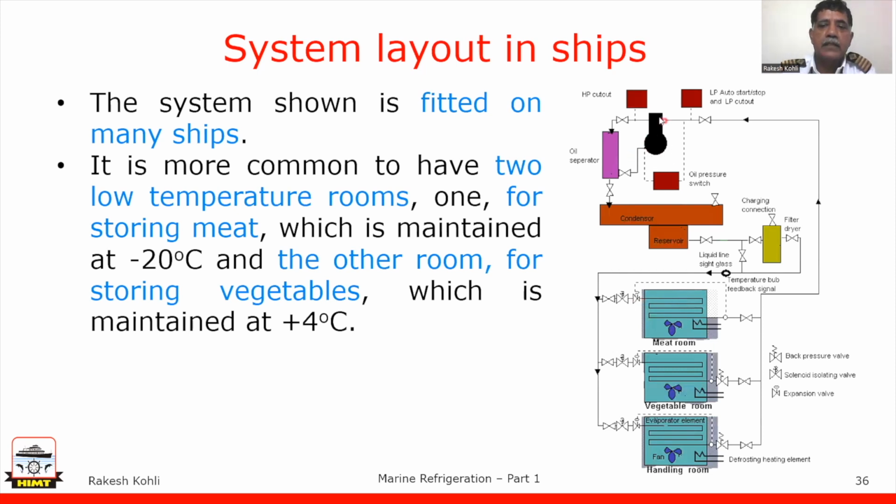In this, there are some additional elements which we need to look at. Say for the compressor, it has three safety switches around it. The most important one, I would say, is the oil pressure switch, which ensures that oil is maintained in the crankcase and lubricates the piston and other parts so that the parts move freely. It's mostly a reciprocating compressor which is used on ships. So the oil pressure will ensure that your parts are free to move and frictionless.